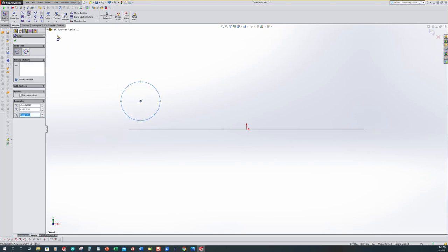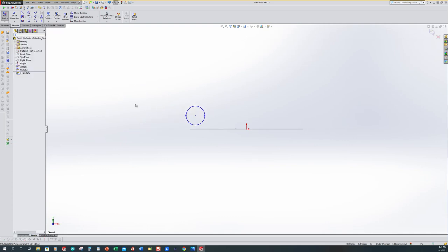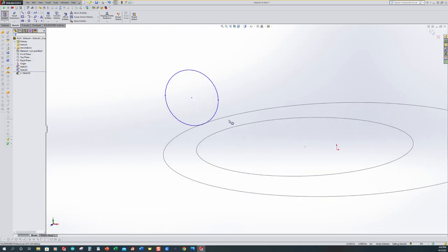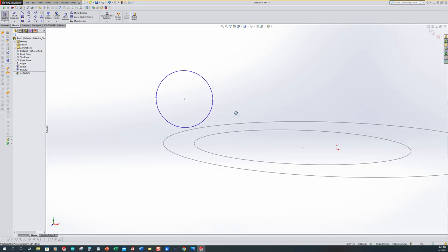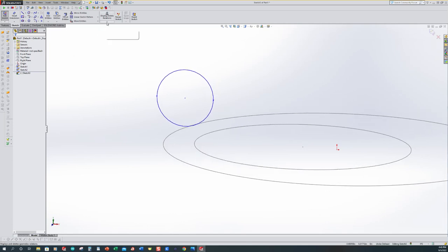And now I want to add a little bit of help. So what I want to do is come up and just add a sketch point, and I want to select over here at 0 and 180 on my circle. So we now have 2 sketch points. I'm going to use my escape key, and I'm going to rotate this thing around ever so slightly where you can see what's going on. So I'm going to use this add relations up here instead of using my control command. That way I can kind of explain a little bit better.